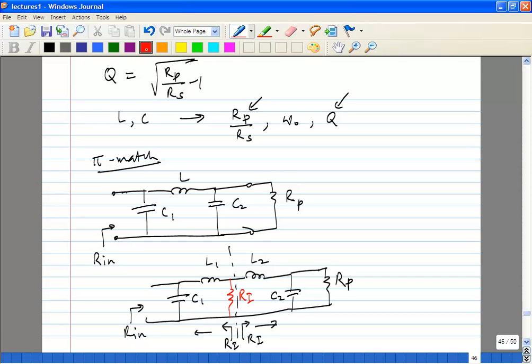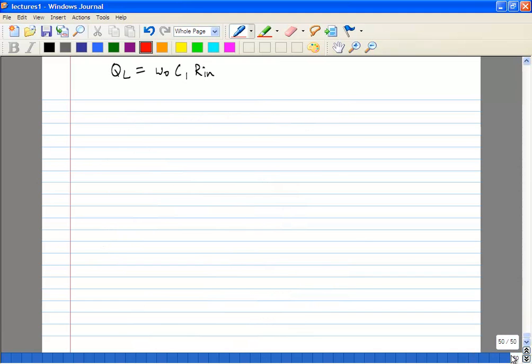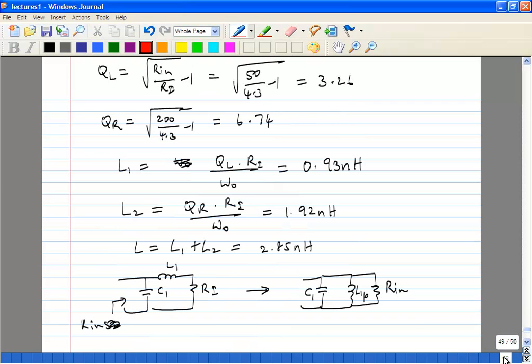Similarly, since this is Ri, you look at this right side network. Again, Ri is in series with L2, so you'd use the same series expression. Is that clear? So we could have directly used the RP and RN. You could have, but the expressions will be different, and what you will get is actually L1P. You won't get L1, because you have to do the resonance, you convert the series to L1P in parallel with Rn actually. That's what we are doing right now.